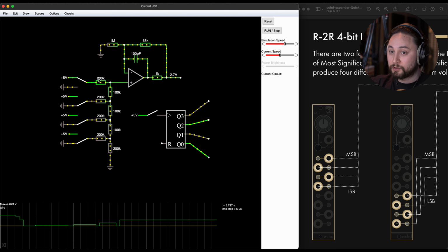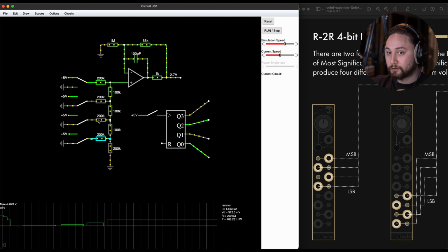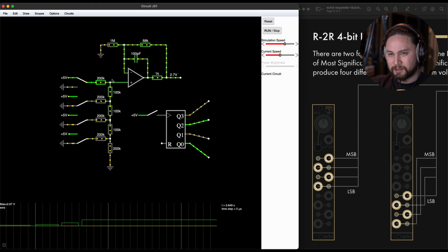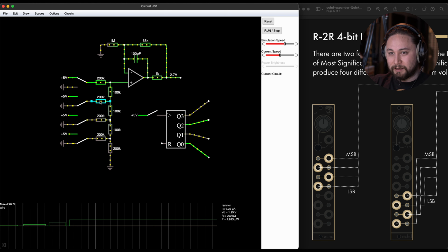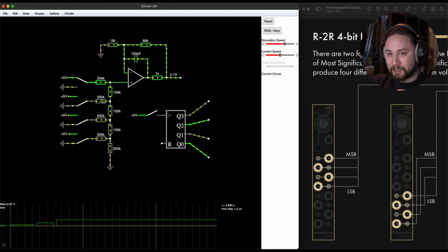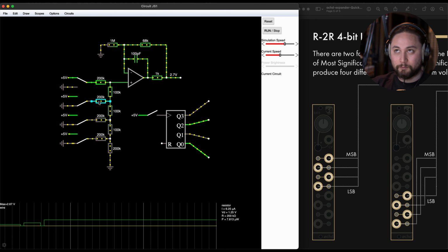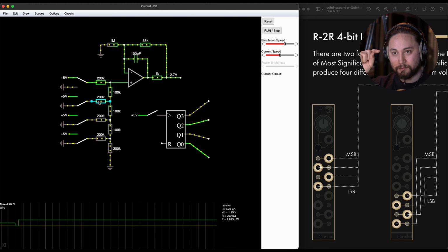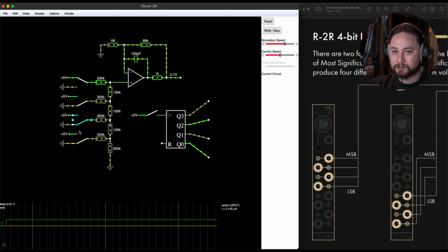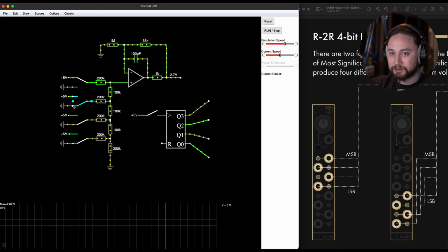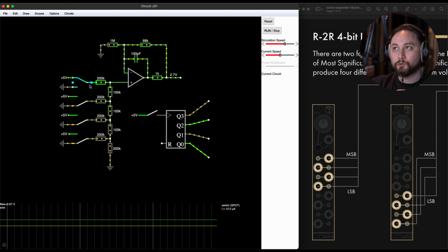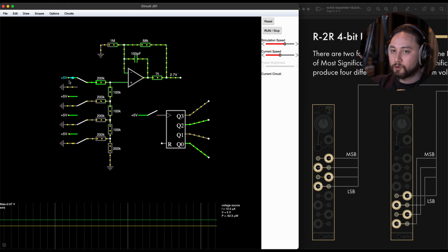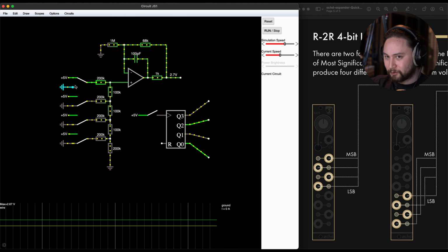And that distribution is coming through this being a voltage divider of 200k down to 500k. So it's a 200k to 500k voltage divider, although it's a bit more complicated because it's actually going, these are to ground, so it's 100k and the rest of that. So it's 500k with 200k in parallel. So we get a lot. It's more than just a static 2 resistor voltage divider. We're getting this sort of complex pattern of the voltages, the individual bits sourcing and sinking current, which is important. That's why I've got a switch that's got 5 volts and ground on it together.